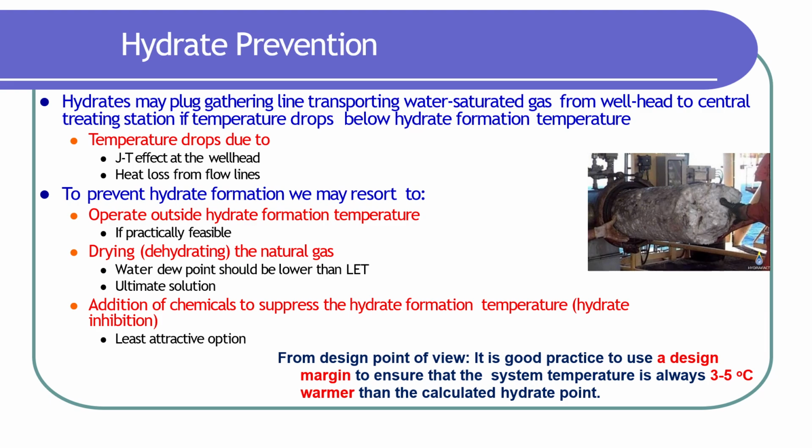So far in the last lecture we have discussed the mechanism of the hydrate formation, and how the hydrate forms. We have discussed also something called the hydrate formation curve. We will discuss the region where it is safe to operate, and the region where it's not safe to operate. We have discussed what we call the hydrate formation temperature and hydrate formation pressure, and we saw how to